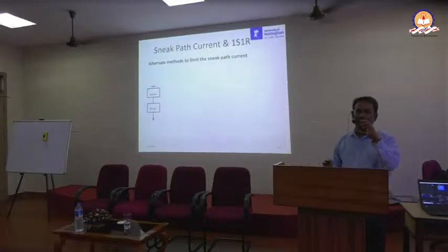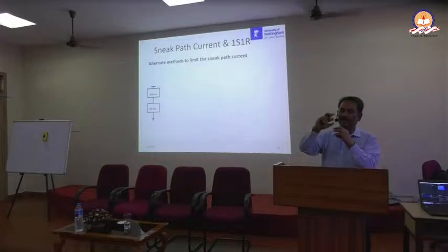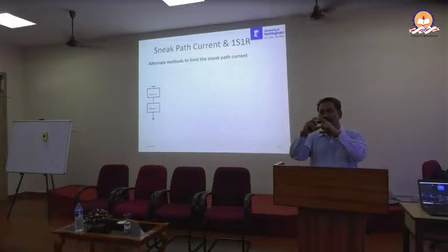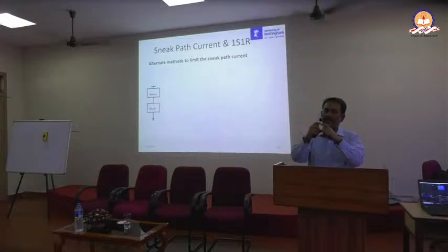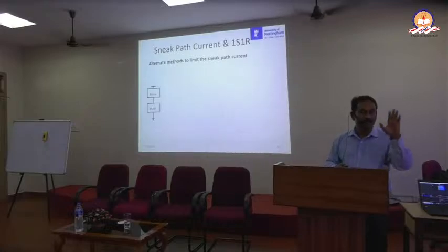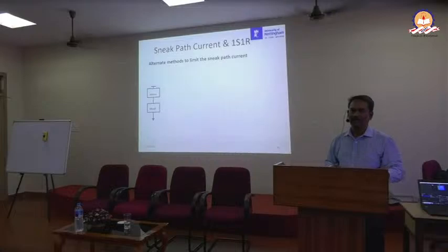Initially we had only one resistive RAM, that memristor, in between the two metal layers, right? Now what we are trying to do is put a selector device there. So the selector device goes in series with the memristor. In each cross section there will be a selector device and a memristor. What is the selector device going to do? It is going to stop the sneak path current. Sneak path current will be there, but it will not enter into the memristance.